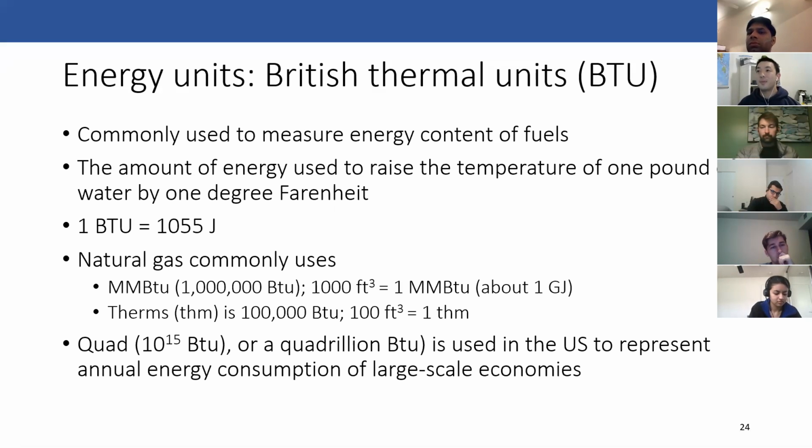So a lot of power plants have this attribute called the heat rate. And a heat rate essentially describes the efficiency of a power plant. When we think about efficiency, and we'll talk about this today, it's kind of like energy in versus energy out. But for a power plant, we think about the energy in, which is the fuel, and the energy out, which is electricity.